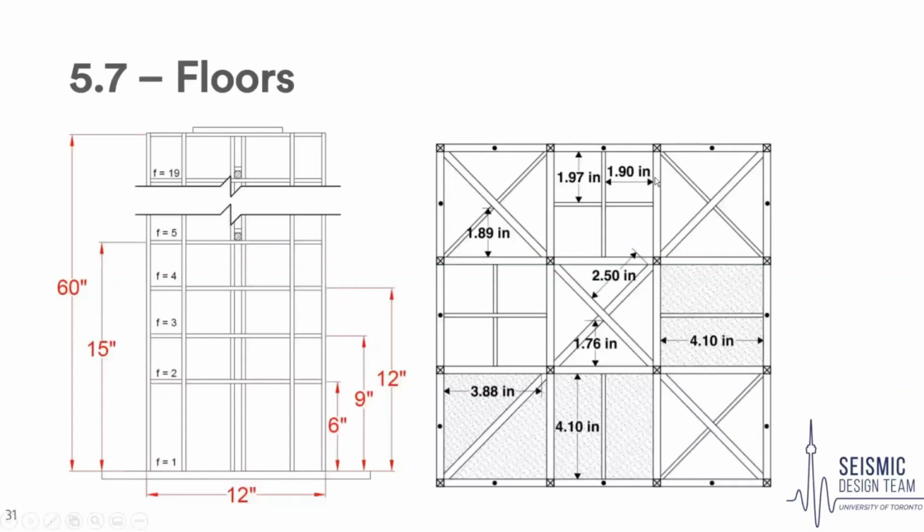If they had this number much closer and it was less than 0.5 inches away, that part wouldn't count. And so you can see these 3 shaded squares are not considered rentable floor area because they don't pass the definitions. And what that means is there's 2 independent floor areas on this floor. There's this one on the top and then this one on the bottom right. So what they'll do is they'll count this one as your rentable floor area, and you basically won't get anything from this because it's not connected to this in any way. You can't get from this one to the other one.